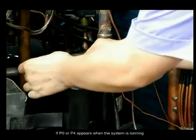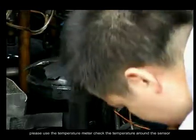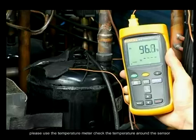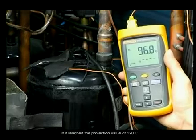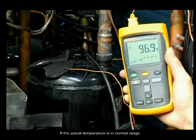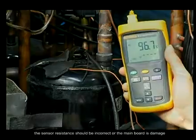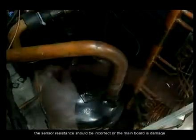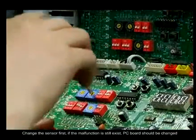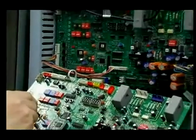If P0 or P4 appears when the system is running, please use the temperature meter. Check the temperature around the sensor. If it reached the protection value of 120 degrees Celsius. If the actual temperature is in normal range, the sensor resistance should be incorrect, or the main board is damaged. Check the sensor first. If the malfunction still exists, the PC board should be changed.